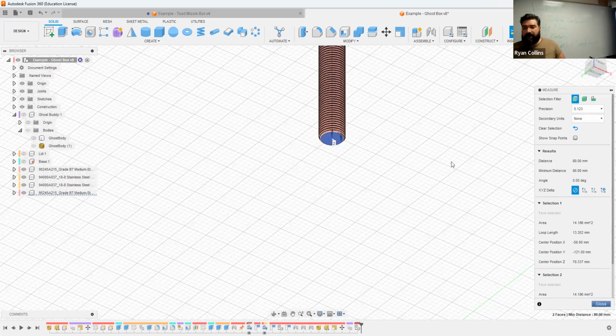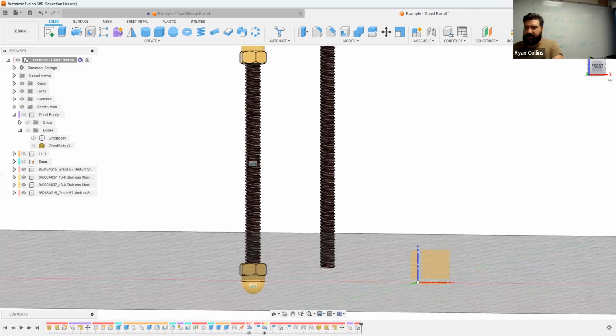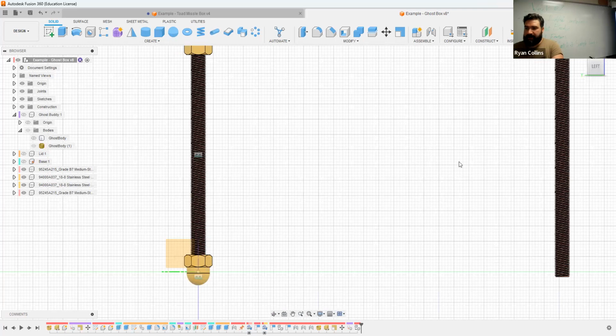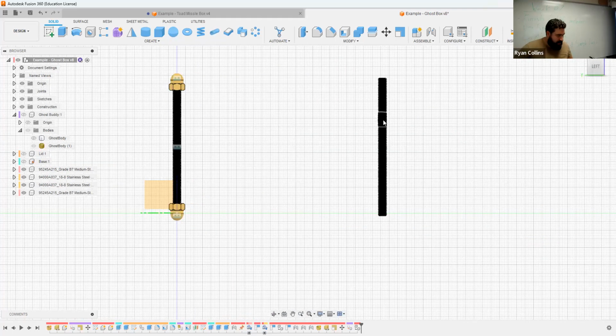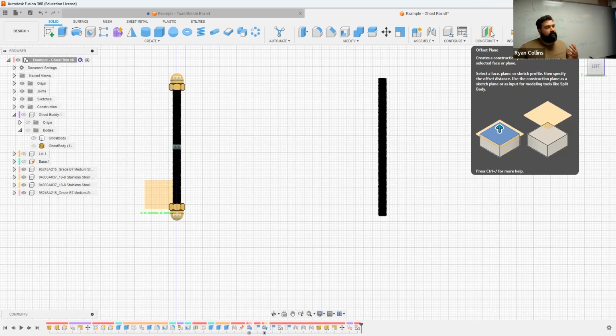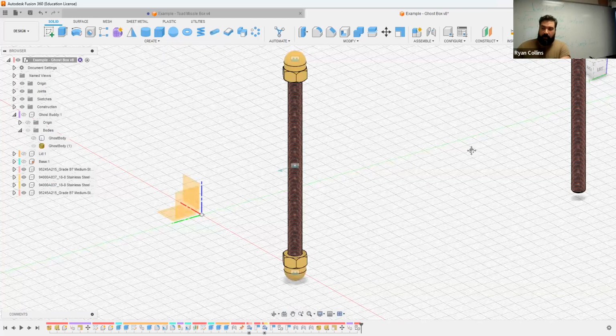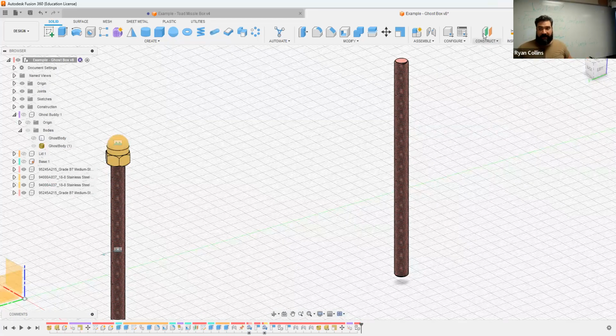Great. Now, technically, yes, I could try to measure from the, oh, that's going to get confusing. Let me go to the left side. I could try to measure down, so much from the one side, or from the center and make sure they're even parts. Don't bother. What I'm going to do is, remember, a construction plane is generated relative to something, so just an offset face even. So it doesn't have to be a plane based off of one of the origin points or origin planes here. We can select a face here and move it down from there. That's exactly what I'm going to do.